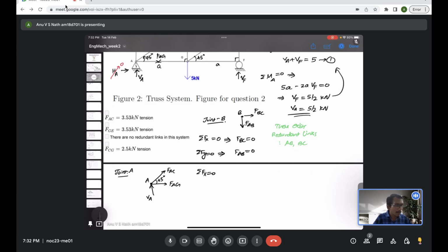For the moment I will follow sigma Fx equal to 0. In some particular cases later I will choose to use the sine rule, which is easier actually. Everything finally leads to the same answer. Sometimes it is convenient to use that simplified equation. So here I will go through the basic one.